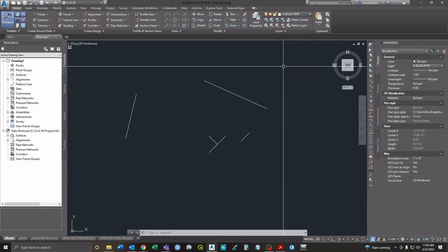So along the lines of that, let's say that I have this center line, and I'm wanting to come 24.75 off of that to actually see where the statutory right of way ends. But let's say that I'm drawing a line out, for instance, and the one that I'm already working on already has a statutory right of way. When I draw a line over that one, and then I make my right of way box, when I go to delete that line from the survey point over, it's not going to delete both lines. It's just going to delete the top line that I put over, correct?